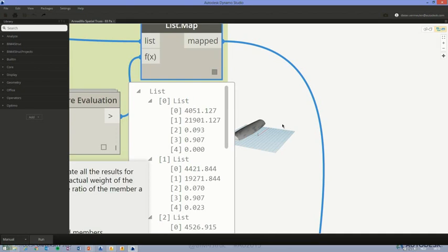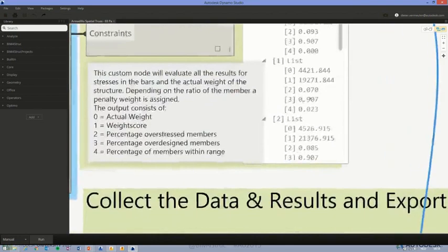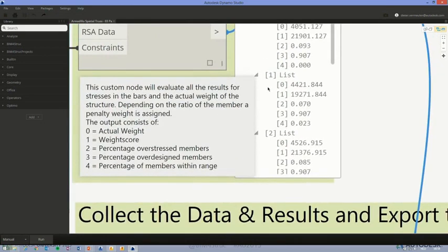Now, I have that list, which is this one. Take all these elements and generate design options for the truss height, truss width, and also with different sections. So if you want to, you can blow up your computer with 2,000 models maybe. But it has to make a little bit of sense, of course. It's a few, so I will only generate 2 options for that. Run it. Then we will see in here the design options.